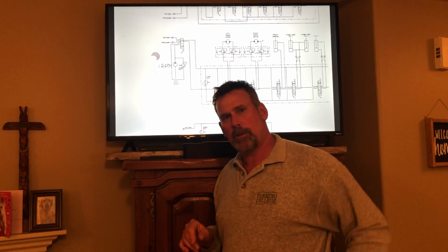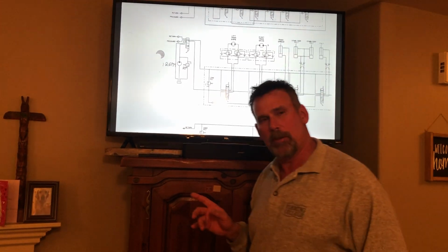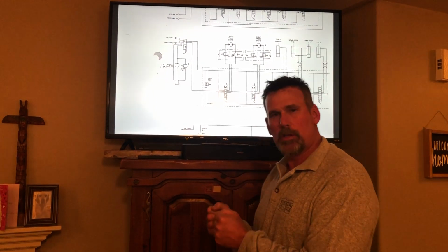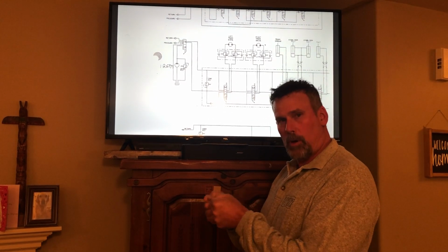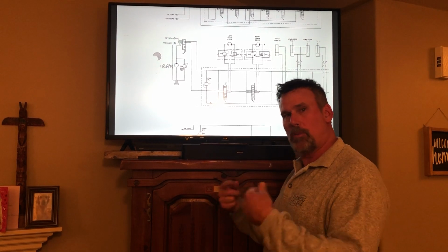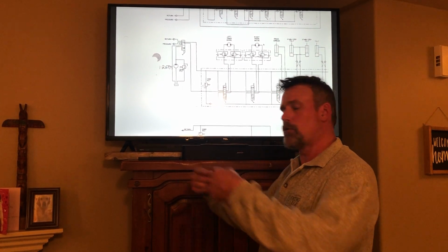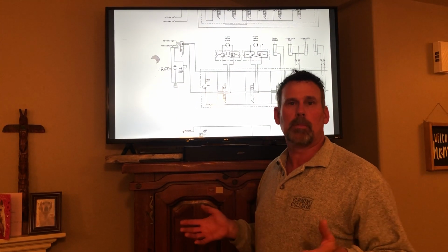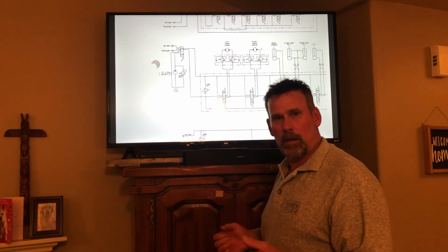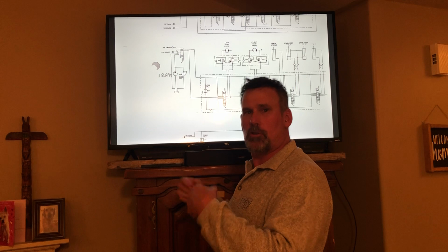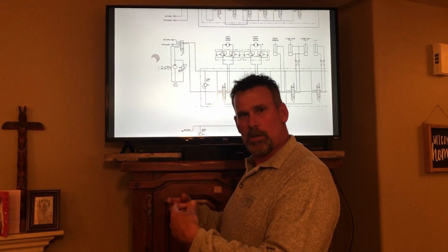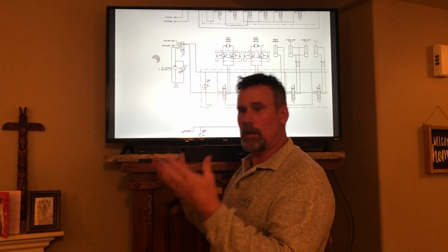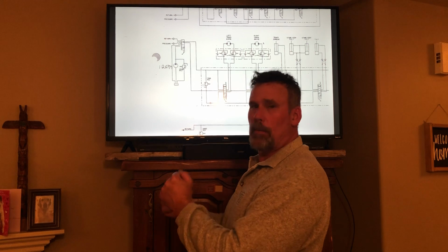Now, the reason for a counterbalance valve we're going to get to in a minute, but first of all, let's talk about, you walk up to the air track drill and you take hold of the levers and you start to move forward. So you're putting oil pressure to the track motors, and the tracks will start to turn and the rig will move. And that's all fine, that's not complicated at all. And now we get to a hill and we start to go up the hill, and the pressure rises against those motors because it's getting harder to push that rig up the hill, but that's no problem. We get lots of pressure in the system, so we go up the hill.